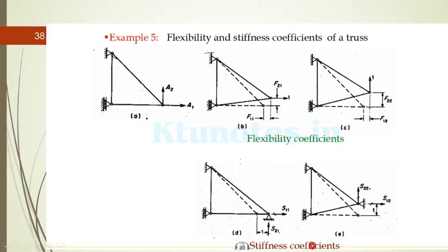For the stiffness coefficient, you know that actually both are axial, so both are actually displacements, horizontal and vertical displacement. For finding the first stiffness coefficient, you should apply a unit displacement in direction A1 and you should restrict the movement upwards, right? And for the second case you should restrict the horizontal movement and you should allow an upward movement for a unit displacement, which are shown in the figures as D and E. Here the unit displacement in the horizontal is permitted, or it is moved, and it is obstructed. There is no vertical movement. In the second case there is a vertical movement, unit vertical movement 1. Here it was also 1 unit movement in the horizontal direction, and there is no horizontal displacement.